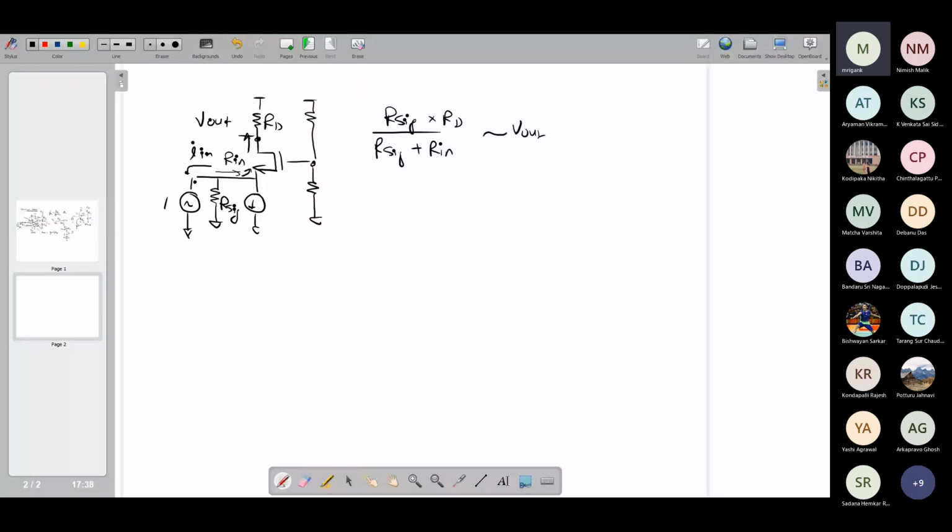And one can understand that because it naturally has a lower input impedance, the use of common gate as a current to voltage amplifier will be, I would say, more popular. And then there are variations of this; when we study feedback, we will look at some of the variations, how you can apply feedback to make it even better. So this common gate amplifier is more popular for current to voltage amplification, that we should definitely be convinced with.